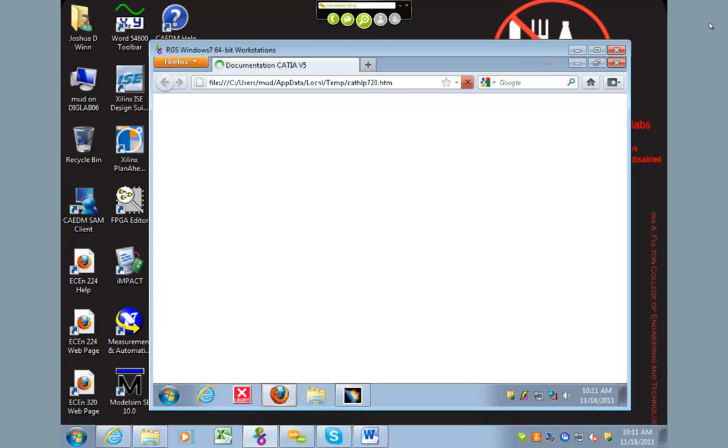and they'll bring up a dialog box that says mechanism, and you can just click new mechanism and name it whatever you want. I just clicked on the Revolute joint. Anytime you click on any joint, because that's the first thing you need to do anyway, it will pull up this dialog box and ask if you want to create a new mechanism.